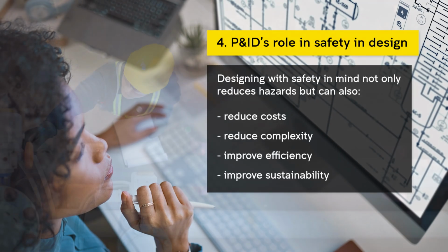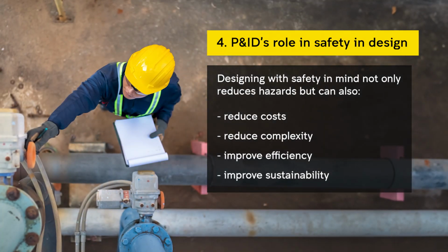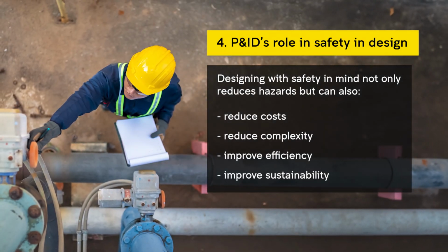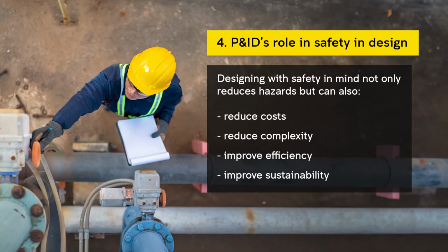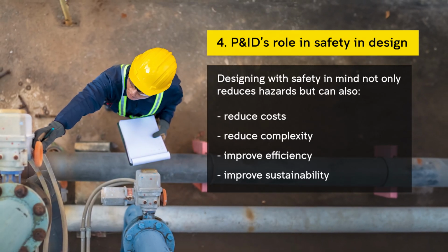So yeah, we're going to put our level transmitters at the bottom of the tanks because it's safer, it reduces the amount of materials that we're going to use, and it reduces the complexity of the design.